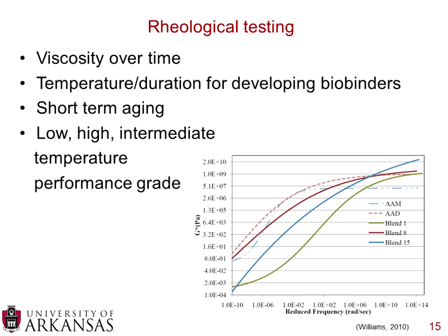For those of you familiar with the SHARP program, there were a dozen or slightly more than a dozen binders that were chosen for the SHARP program, the Strategic Highway Research Program in the mid-1990s, which developed the PG grading system, and they used these specific binders that had a wide range of properties. And they specifically chose them because they wanted to make sure that the SuperPave testing system was able to properly capture the properties of all of the asphalt cements that are used across the country.